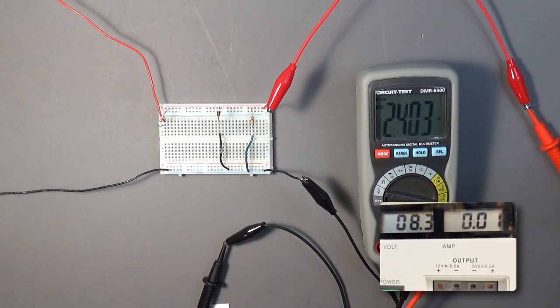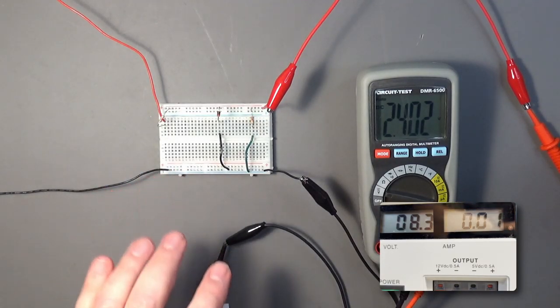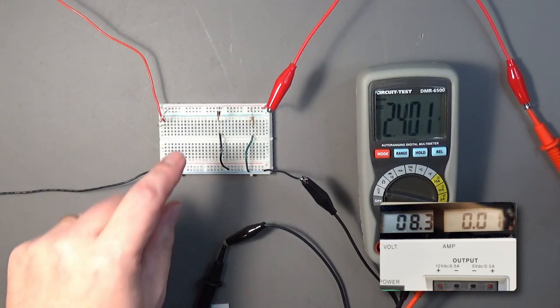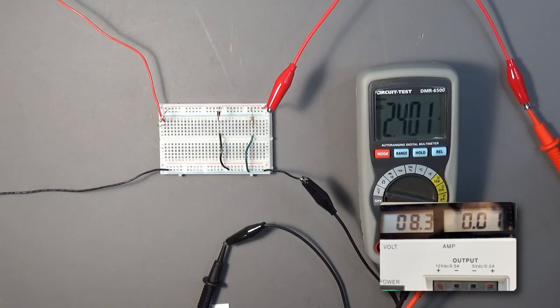And that's one of the things that Zener diodes get used for. Now, it's not very useful in a simple circuit like this if there's a lot of current, because the Zener diode can't really handle that. But they're used to provide voltage references in power supply circuits. And if we go back down, they'll start matching up again pretty close, and then back down to off.